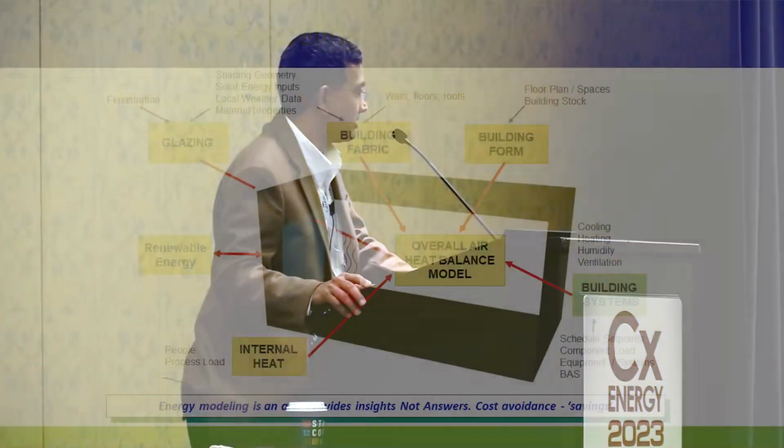Once we do this, it goes to ongoing commissioning, or MBCX, where we do proactive maintenance. We continuously collect data, and we can move on to fault detection and look at sustaining energy savings. And the cycle repeats itself, depending on every couple of years or as the building usage changes.